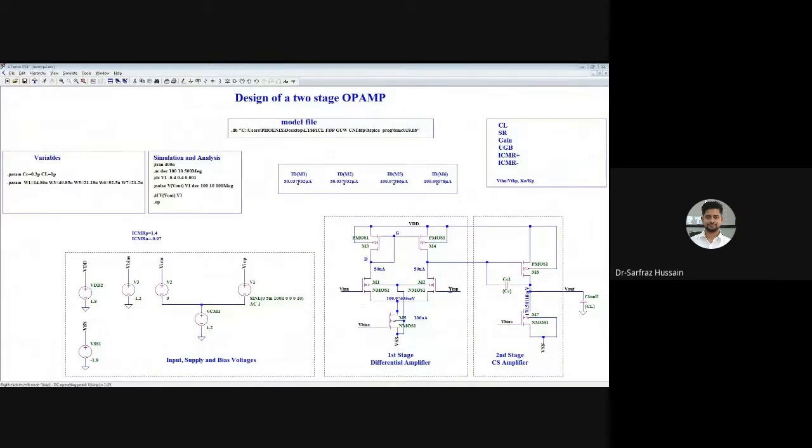So once we get the current value, we will get the slew rate values. So this will also give us a slew, and this will also give us a slew, because here also we have a capacitor, here also we have a capacitor, and this is dependent upon this. So we'll consider this particular capacitance, that is the feedback capacitor over here. Okay, and this capacitor we will use to find the slew rate.